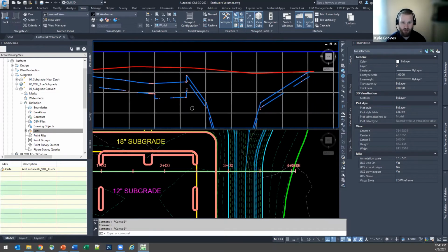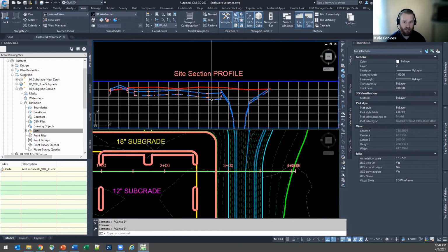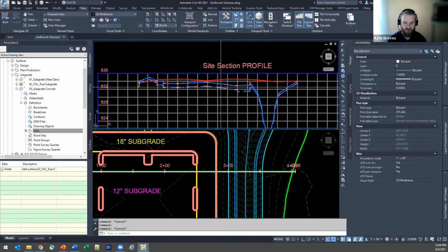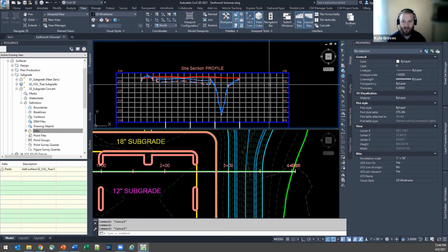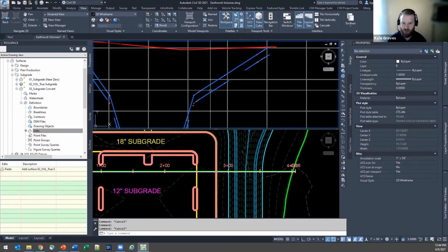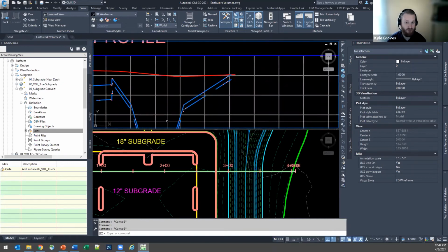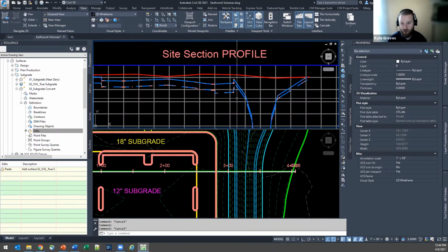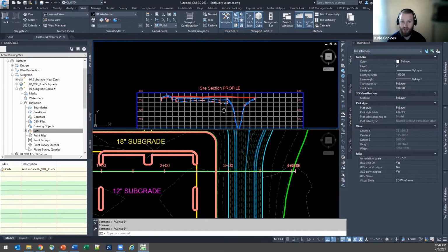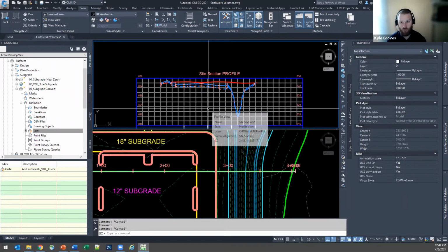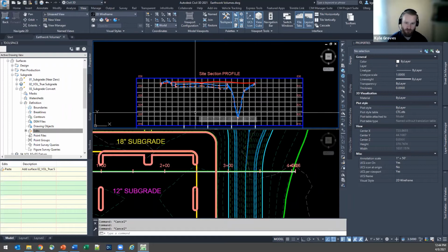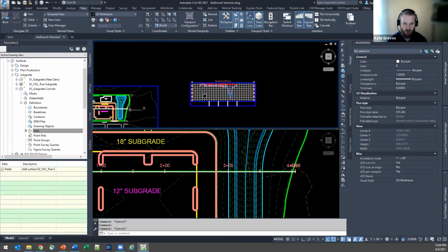So this is telling me that I have correctly identified and correctly modeled those various subgrades. So that's good. And then I'm going back into my 6-inch because it's standard topsoil in my detention basin area. But this profile view is telling me very clearly, hey, I am extremely cut heavy. I will want to do a lot to try and bring this site up. Otherwise, we're going to be getting a bunch of soil out of here.